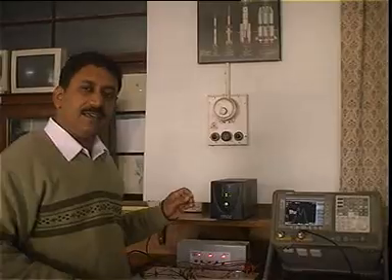So I gave the input to the product modulator. The input consisted of the carrier signal and the modulating signal. And at the output of the modulator, I had the AM signal. Now, if you were to transmit this on a wireline channel, the channel will be, let's say, a twisted pair of copper cables. Then I have the output of the modulator straight away feeding into the copper cable.